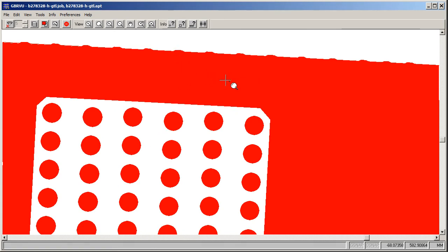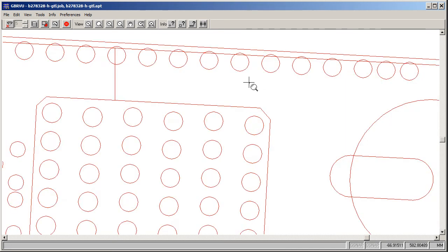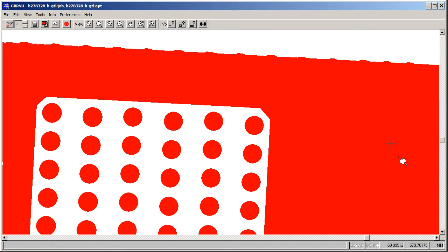This file is built up of multiple layers, and if I turn the fill off, it's likely that there were some pads placed first on this layer, and then later on some filled in areas of power plane. You see that the pads are leaking a little past the edge of the power plane there. Same over here, you see a bunch of stuff that gets covered up. Both ODB and Gerber support multi-layers of what we call paint and scratch. So let's look at the bottom layer now.